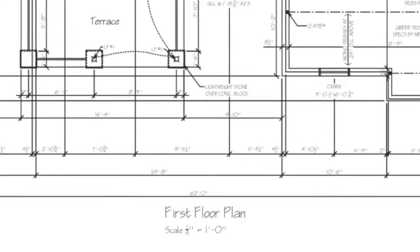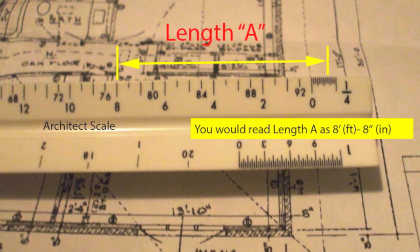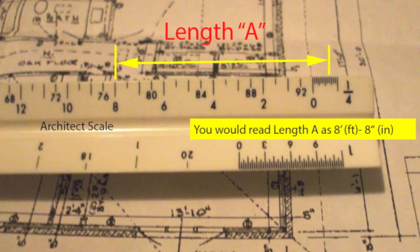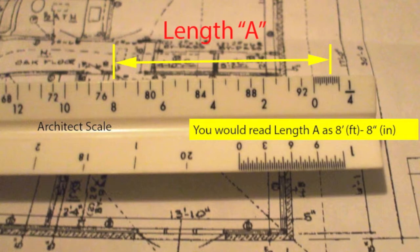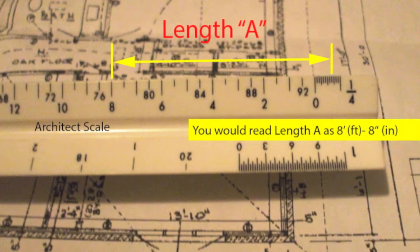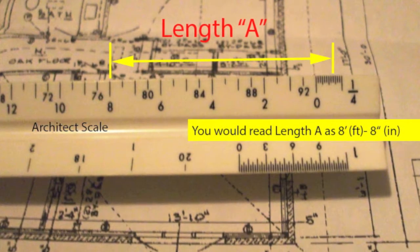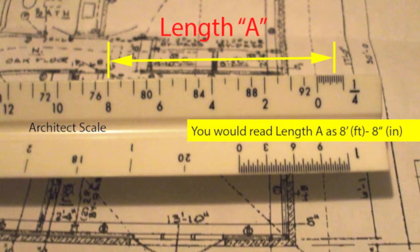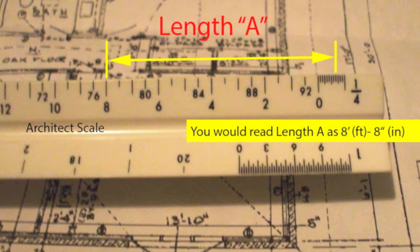Now let's do a few measurements using the architect scale. Let's do a simple scale reading exercise. Note length A in this image. Also note that we are using the 1/4 inch side of the scale. Length A starts on the number 8. Each graduation on the elongated portion of the scale represents 6 inches. Read from 0 to the left as 6 inches, 1 foot, 1 foot 6 inches, and so forth to 8 feet in length. The line ends on the 8th tick mark or graduation after 0 to the right. From 0, simply count the number of tick marks to the right. I count 8. You read length A as 8 feet, 8 inches.